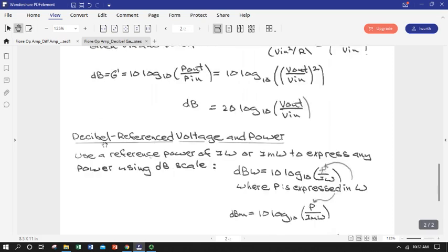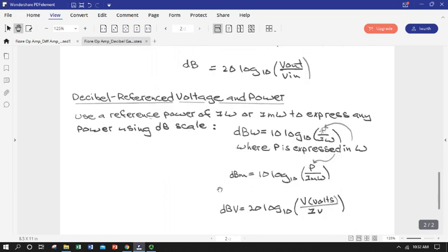And then if you're using the decibel scale to reference a single voltage, a single current, a single power, it is essential that you tell everyone what your reference is so they know what's on the denominator. And if somebody cites a power or a voltage or a current on the decibel scale and doesn't tell you their reference, ask for it. Don't assume, because it could be off by 3 orders of magnitude, which would be a bad mistake.